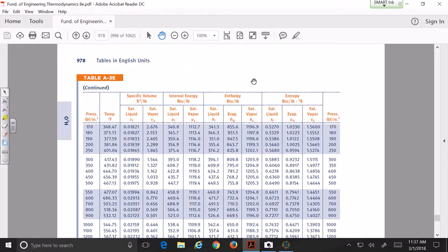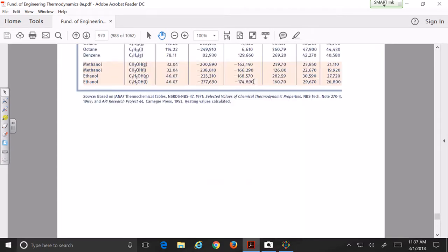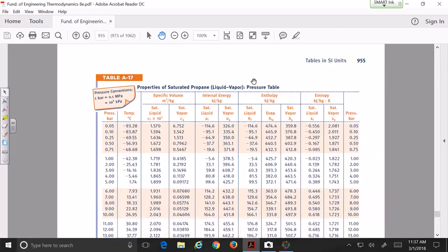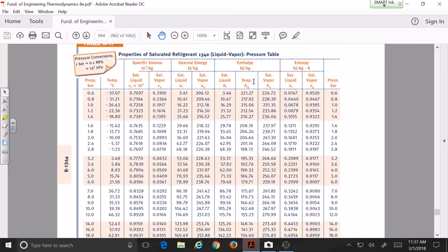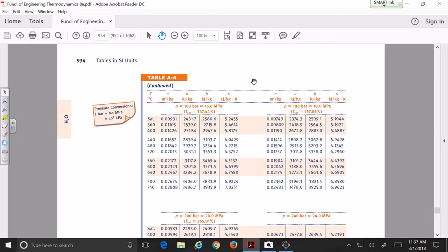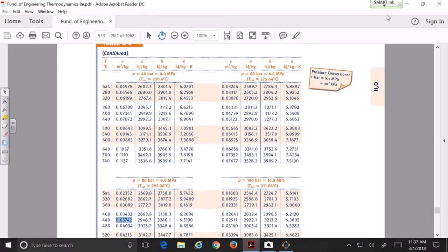And this is English unit, so you see I was completely off with the... It should be around 9. So let's see, if the pressure is 60, we can use this one. What is the saturation temperature? 275, no? But the temperature we have is 400. So what does that mean? State 2 is still superheated, no? So what would be V2 for in this case?